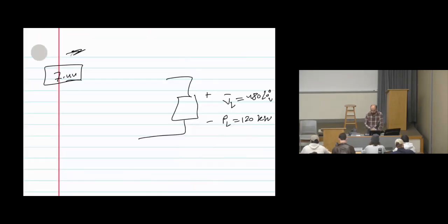Here we have the real power, 120 kilowatts. Having one quantity, since it's complex power, we need two quantities: something related to the magnitude and something related to the angle, or something related to the real part and something related to the imaginary part, or a mix of them. So we have only one piece of information, 120 kilowatts. We have another, which is the power factor of the load, 0.84, and it is lagging. Now, when I have these two pieces of information, I can find the complex power. Let's finish the question, then we will see how we can find the complex power.